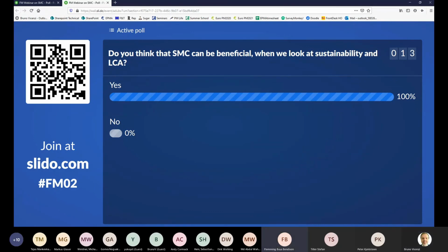So if you think about a motor made of SMC, you can actually crush it, and then you can take out the windings. If you try to crush laminations, they will not break. It's more, let's say, ductile.